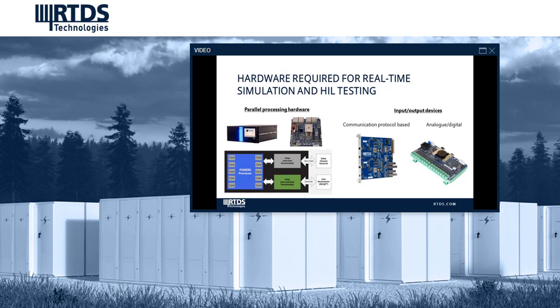And the I/O can be based on communication protocols or more traditional I/O involving analog and digital signals. So for example, you might send system voltage and current or real and reactive power values for distributed energy resources from the simulated system to the physical device under test, and you could do that using analog quantities via our analog output card or using a protocol like DNP3. And you may wish to send breaker commands from the device under test using our digital input card or with a protocol like IEC 61850 GOOSE.